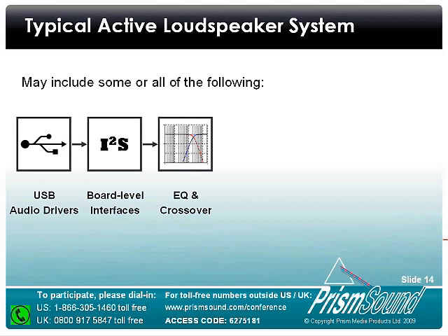Being an active loudspeaker, there is a very high probability, almost a certainty, that there will be some equalization or filtering applied, either in DSP or potentially in passive or active crossover networks, to distribute the spectral content of the audio signal to the appropriate drive units for the frequency bands that we're interested in reproducing. In a more simple system like the one I'm looking at today, there may well be some EQ in there to prevent the drive units from receiving too much power at low frequencies where they cannot handle the excursion, and likewise to increase the headroom of the amplifiers by limiting the frequency range of signals the amplifiers attempt to reproduce.